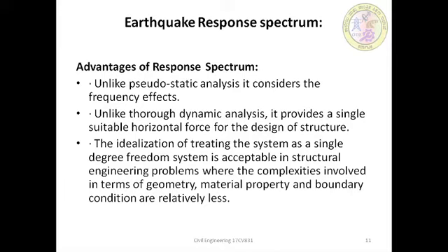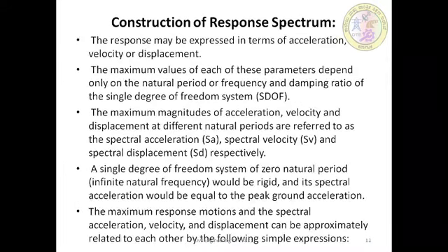Then the idealization of treating the system as a single degree of freedom is acceptable in structural engineering problems where the complexities involved in terms of geometry, material properties and boundary conditions are relatively less. So this is all about what the response spectrum is and what its advantages are. Then how is the response spectrum to be constructed?